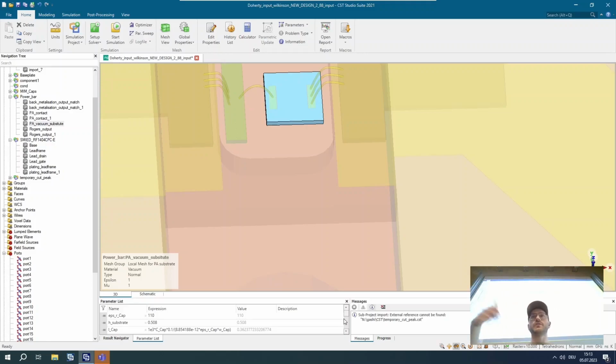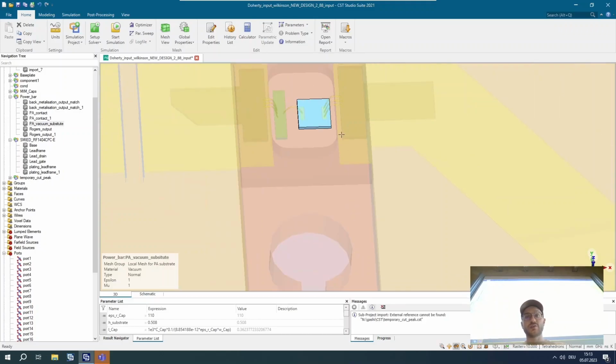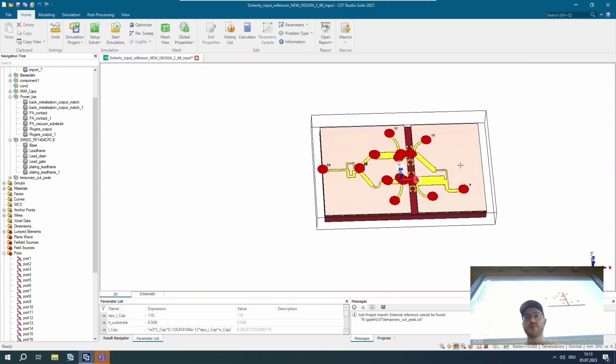You have a certain technology that you can access. In that technology, you probably have certain information about how much thermal load is produced with respect to gate width, when the respective voltage bias is applied. You input that information into the solver, and you tell the solver, hey, I generate this amount of heat, and then you define your packaging as the sink. The sink is everything that is metallic here.